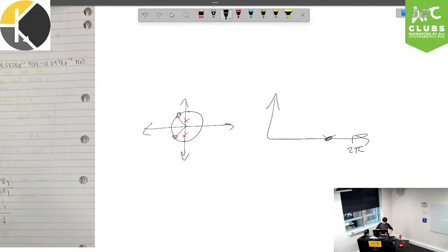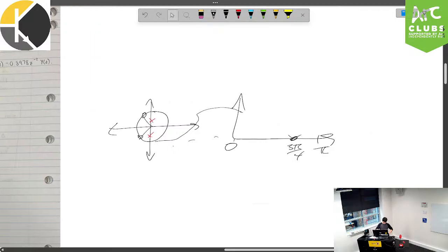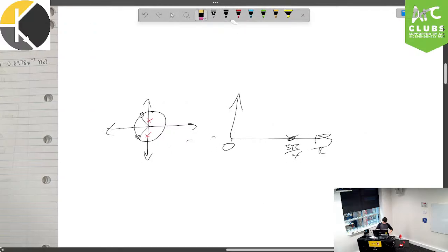This is going to be from 0 to pi. This one will be 3 pi on 4. And just by the way, we know we're only going 0 to pi because we understand that the magnitude response is an even function. So in other words, it would be mirrored on the other side. And we also know it's periodic, okay? So nothing too much to consider there.